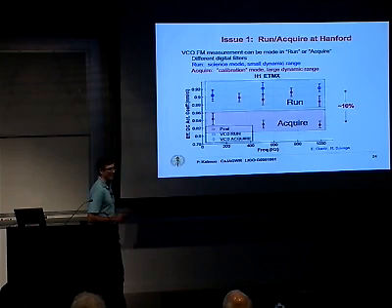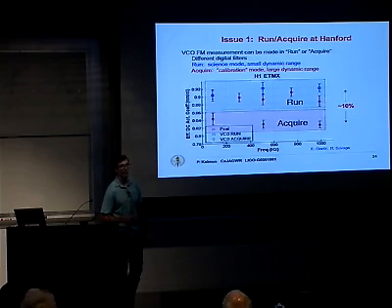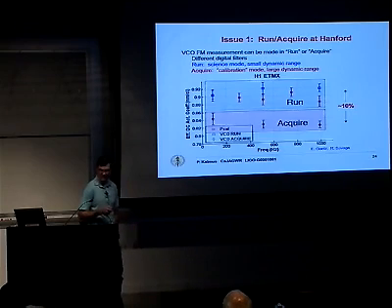So Evan Goetz, I guess at Hanford, went out and did that. He took some VCO calibrations at a bunch of frequencies with the electronics set to run, and then with the electronics set to acquire. The digital filters are different in those two modes, and he found approximately a 10% difference in what the VCO said in those two different states.